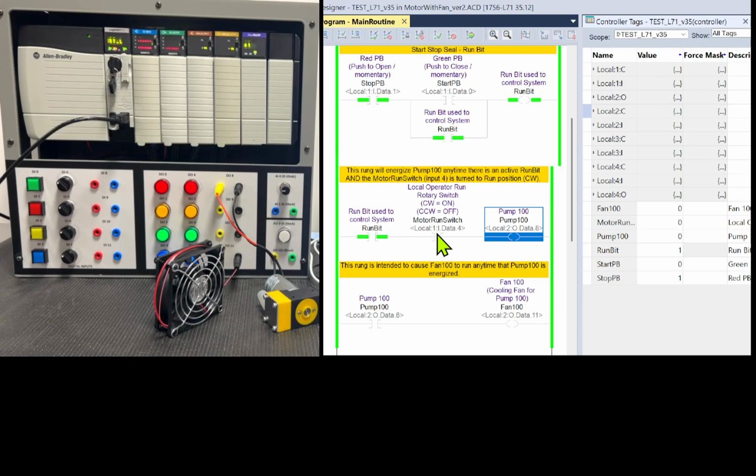When you force outputs, there's a lot of weirdness that can happen, and this is just one of them. A lot of times, for not great reasons, outputs show up more than once in a program, especially if programmers come from a world where they do a lot of jump type stuff and a lot of different subroutines and calls and things like that. They tend to do that a lot. It's bad code, but you'll see it. I've been with Fortune 100 companies, and this kind of crap is all through their programs. It's crazy, but it's there.